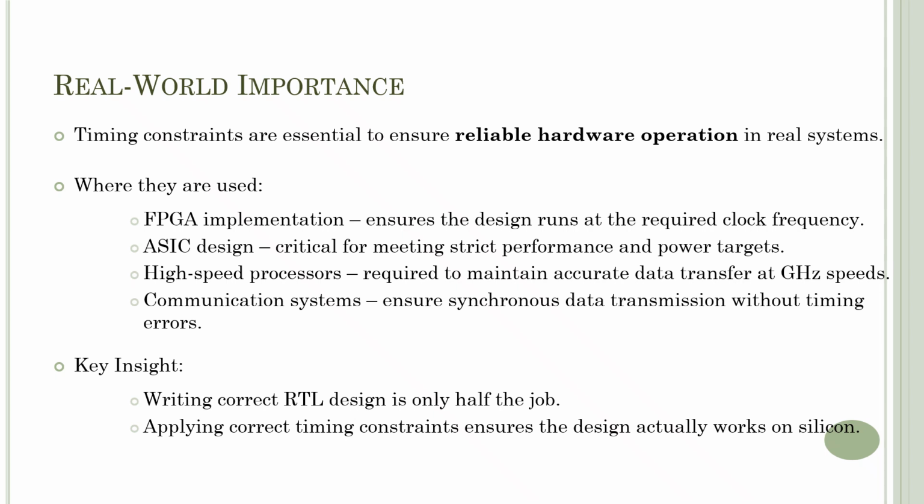Second, timing constraints are very important in ASIC design. In ASICs, designers must meet strict performance, power, and area requirements. Proper timing constraints allow the design tools to optimize the circuit so that it can achieve the required speed while maintaining efficiency.